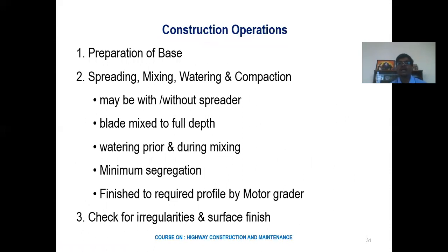So these are the construction steps for the crusher and macadam. As usual, the first step is preparation of the base layer, the receiving layer, that is the sub-base layer, or the bottom granular base layer. So we have to prepare the base. What do you mean by preparation of the base? We should check for the longitudinal grade or the cross profile, and any distresses in that layer. All those are to be rectified before constructing the new layer. That's the meaning of preparation of the base.